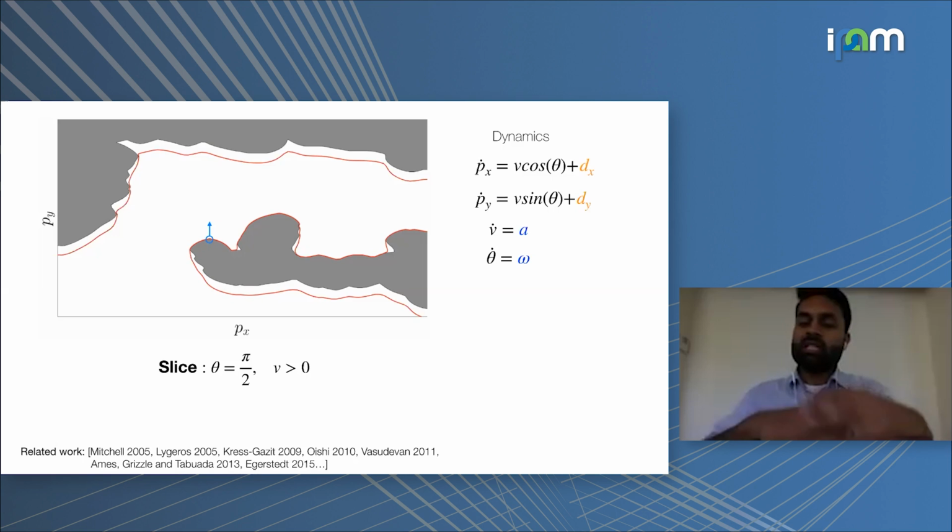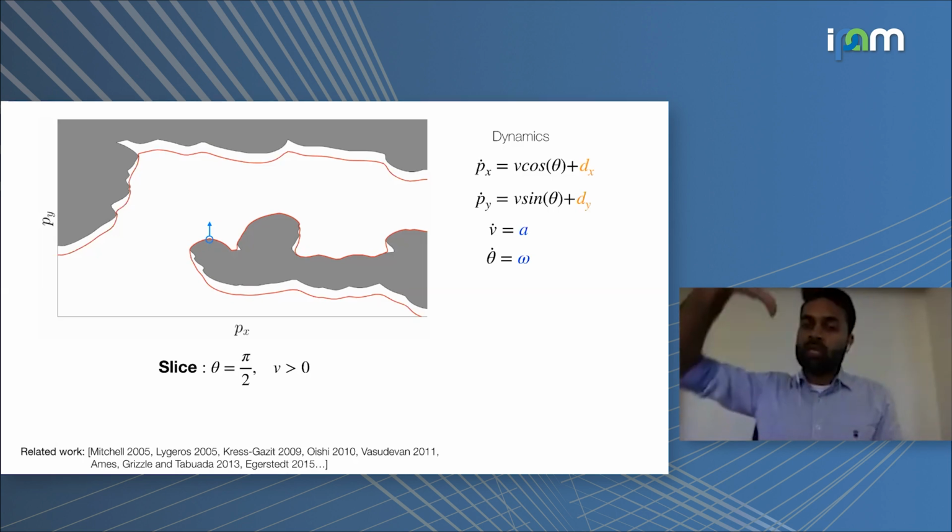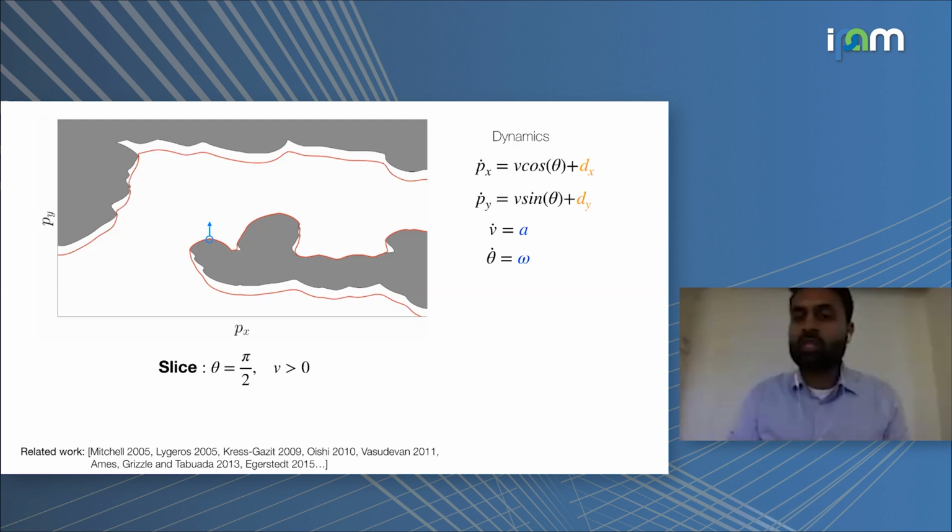If I were to see the same slice of the backward reachable set, but with a heading of -π/2, meaning the robot is facing towards the bottom of the screen, then you will see a retraction in the boundary here, whereas the boundary of the backward reachable set will hug the obstacle boundary in this region. Now, obviously, the idea of backward reachable set and Hamilton-Jacobi reachability is not just limited to this four-dimensional system. We can, in theory, apply it to any autonomous systems. And that's what we're going to see next, like how we can actually do that.